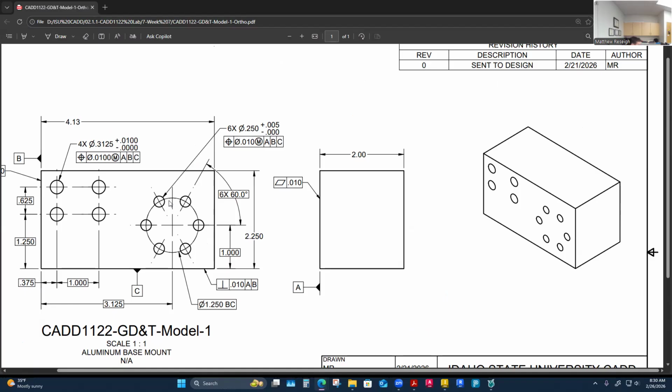And the reason is because the fabricator actually has an easier time installing something that's two-hole rather than single-hole, because they have these special tools. They're called two-hole pins. And all they do is bolt into these holes. While they're fitting up a flange to a piece of pipe, they would bolt this tool through these two holes right here.